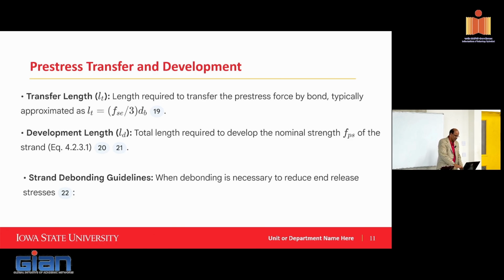They provide debonding guidelines for the reason I mentioned, because precasters use debonding as a technique to minimize the effect of local stresses.